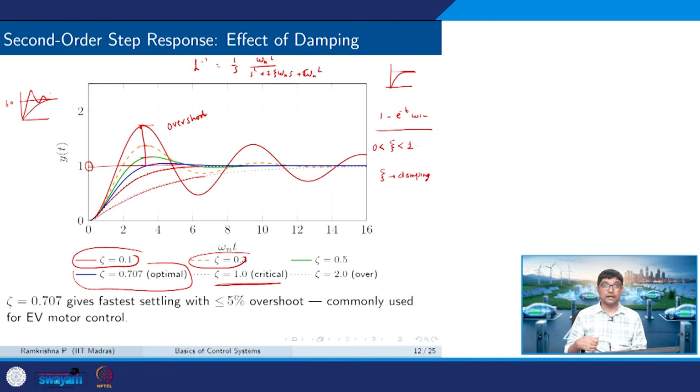Now, similarly, if I take an air conditioner, I am allowed to have a faster response. Outside is 42 degrees, I come inside, it's boiling hot, I switch on the AC, I want the temperature to go down very fast. And say my set point is 21, it is allowed for it to go to say 20 or even 19 and then settle down eventually to 21.